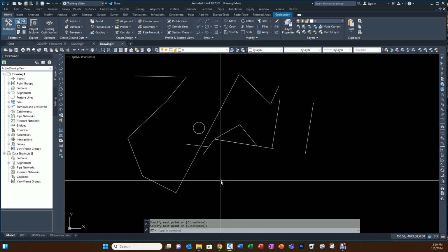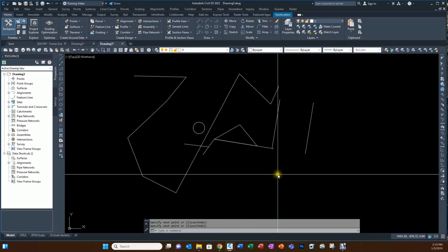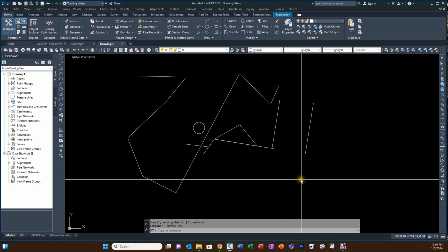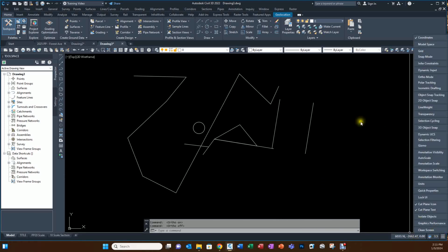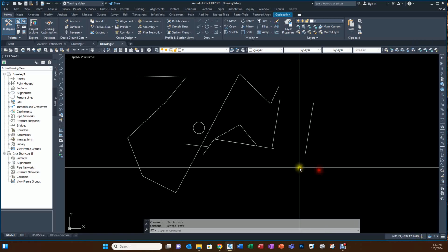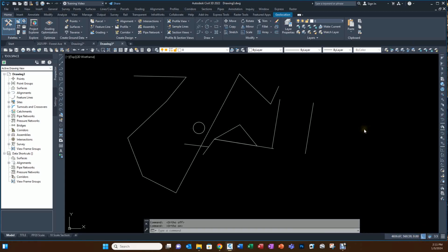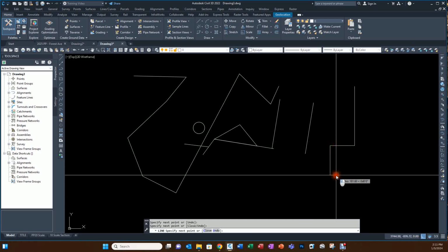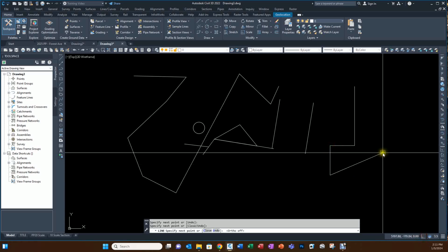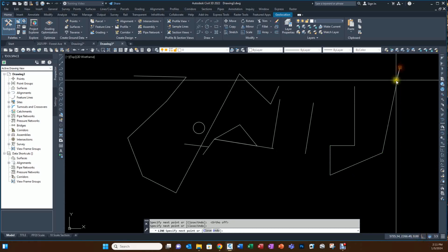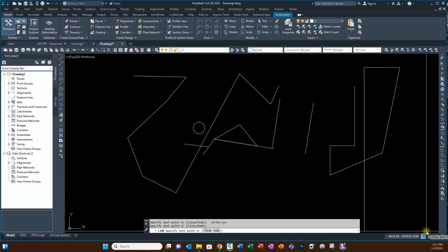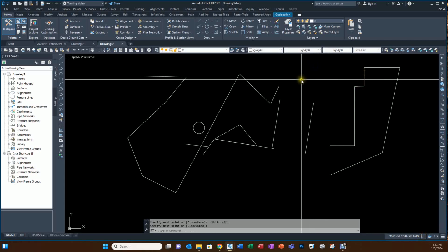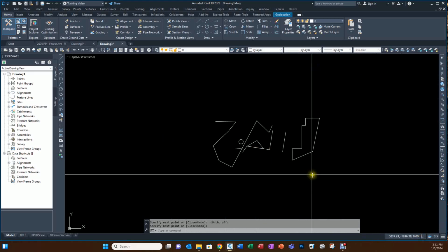But anyway, there's a way to hold the shift key down, and it'll go into kind of a temporary ortho mode. But F8 is your ortho on, ortho off. If you can't remember that, or you're new to it, you can go to the ortho mode here, and it will show you as an icon. If I want the ortho mode on, I'm doing that, and if I want it off while I'm in the command, I can do that, and then go back to ortho mode and close the gap. So there are choices to be made here as you're drafting.